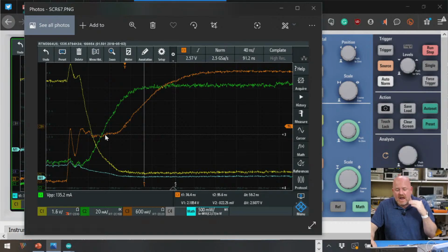Unfortunately, every manufactured MOSFET is going to be different. If you look at the datasheet, just like the VGS threshold, there's a range in which the MOSFET turns on. Until you measure an individual MOSFET, you don't know what it's going to be. Which is another reason why you would want a series resistor that would allow you the potential to do some kind of adjustment in manufacturing.